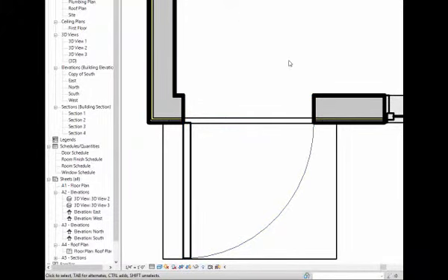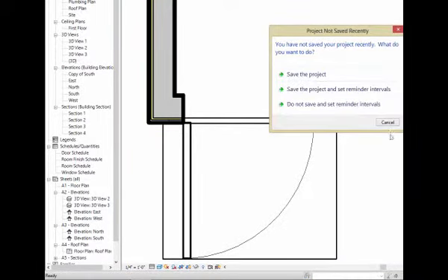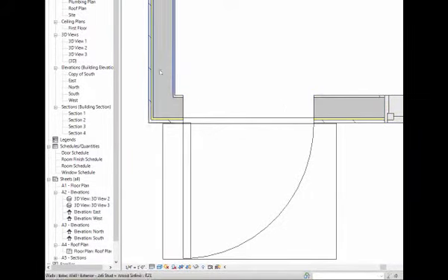And what I'll even do is switch this view. Currently you can see the walls have a pretty heavy thickness. I'm going to change to something called a thin line view, where it'll shrink the edges of the wall down so I can see more accurately where those boundaries are.